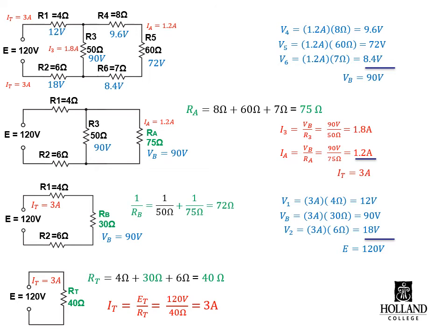Simplify down to an RT. Keep track of your changes. One change at a time. Use values that you calculate in one of your simple circuits to move back one step and find unknowns in the circuit before. Follow these simple rules and it works out to be pretty easy because all you're doing is EIR.